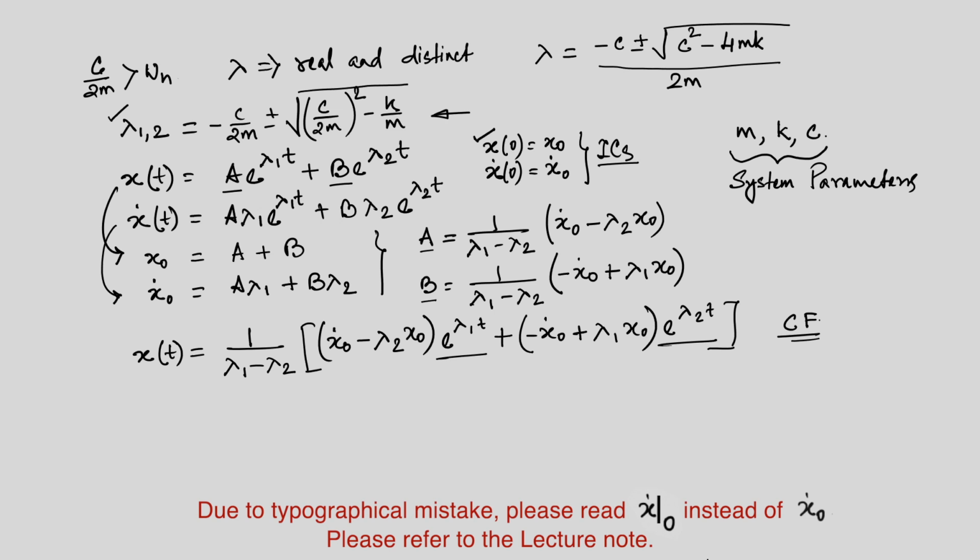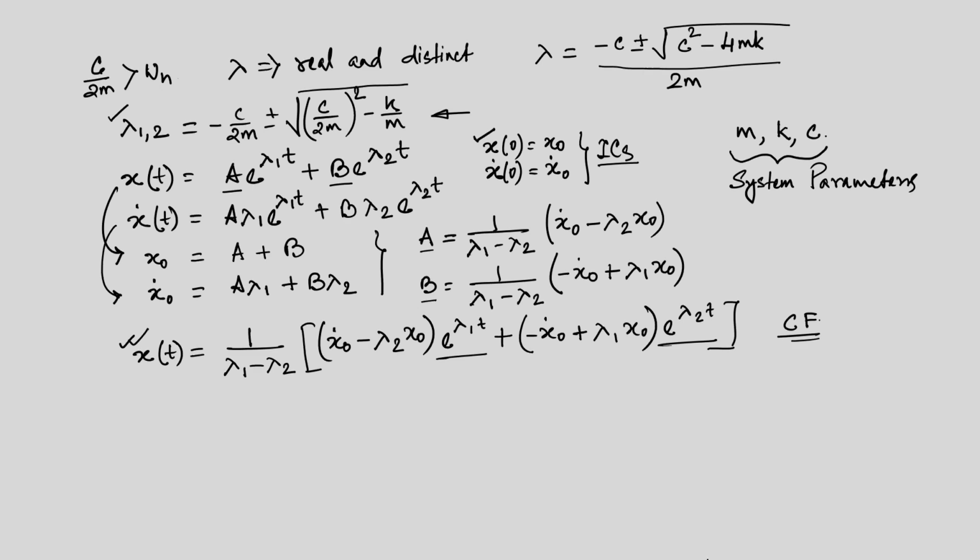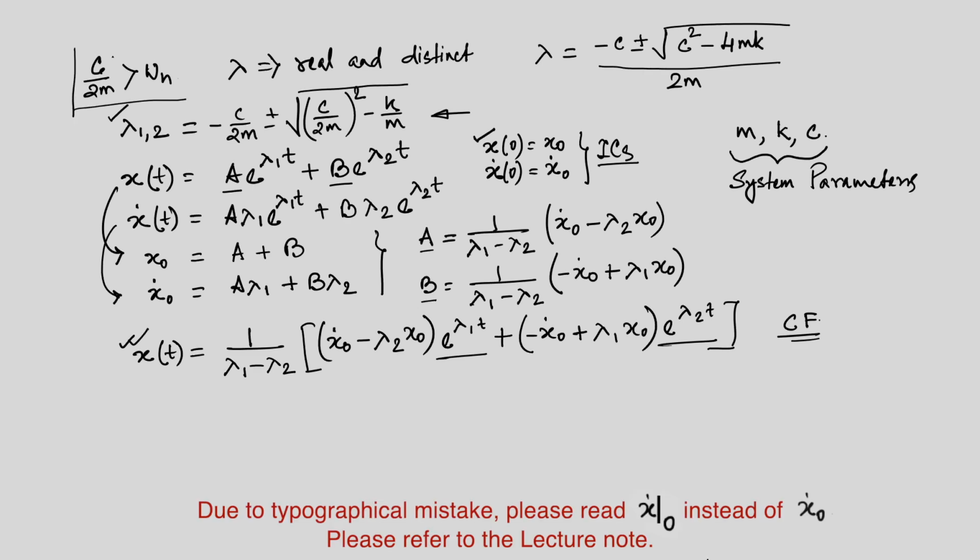Now, if you look at the right hand side of this solution, you will see there is no oscillating component. If you recall the solution we did in the last class for the undamped free vibration case, the right hand side was sinusoids. So, as t progresses, a sinusoid will continue its oscillation, but here, the moment we have an over damped system, first of all we have damping, and the damping value satisfies certain criteria which is marked here corresponding to over damped system.